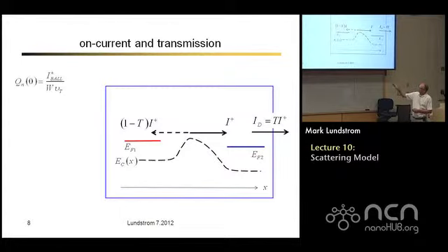In the ballistic case, we injected some positive flux. I'll call that I plus ballistic. And current is just charge times velocity. So if I divide that injected current by width times thermal velocity, that's the charge at the top of the barrier. Under ballistic conditions, it's only positive velocity electrons. Now when I have scattering, I have a positive flux and I have a negative flux. And both of them contribute charge, so I've got to add the two together.